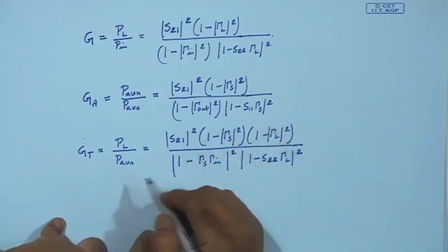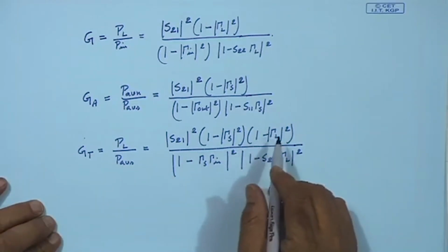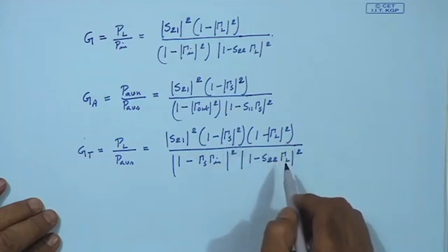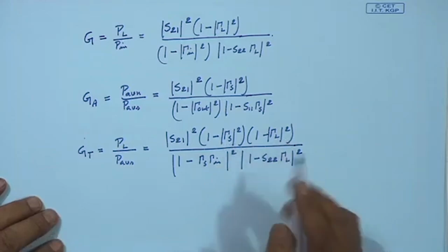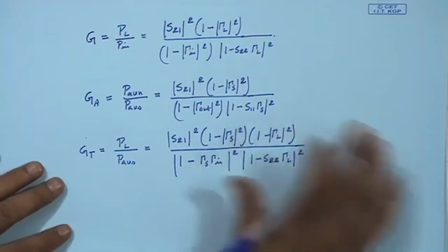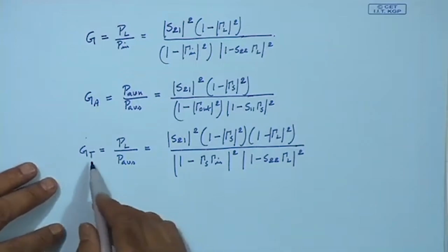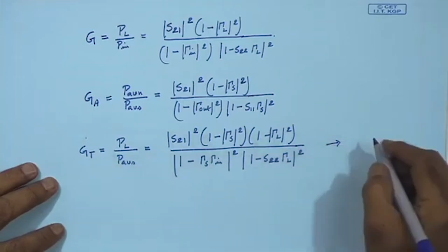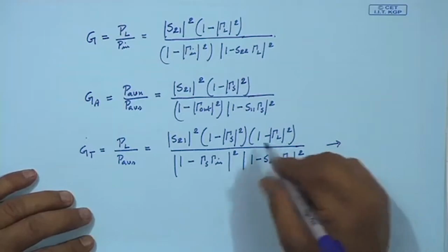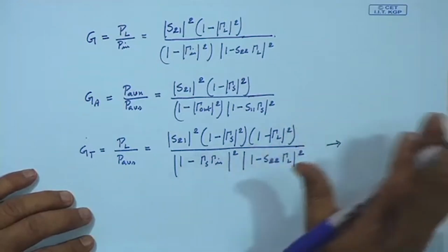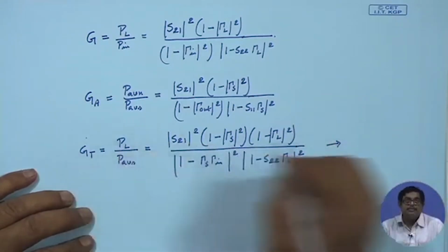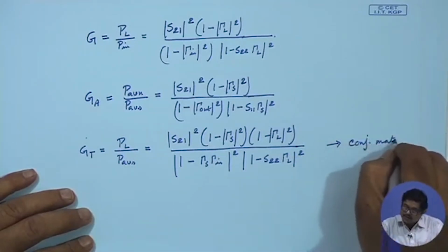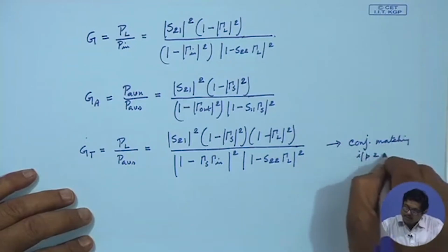as said. You see this transducer power gain is dependent on both load and source impedance. That's why it depends on both gamma S and gamma L, gamma in, everything is included here. Now you see that sometimes this is the maximum gain possible, GT, for a particular gamma L and gamma S which are conjugately matched with the input and output impedances. This is the maximum that we can achieve, and please remember that this is for conjugate matching on input and output side both.